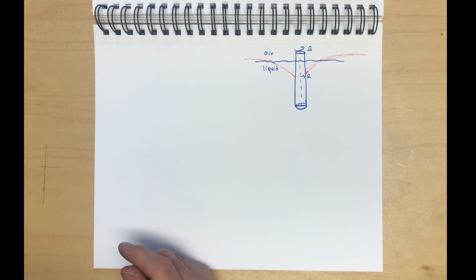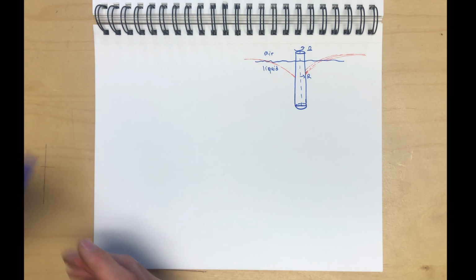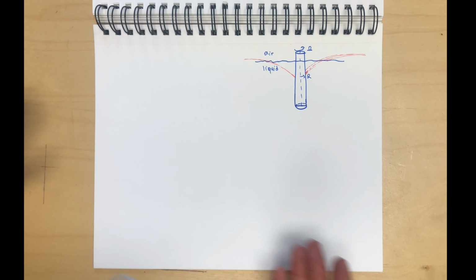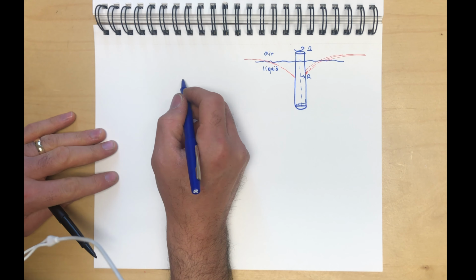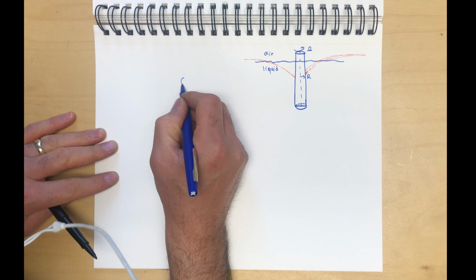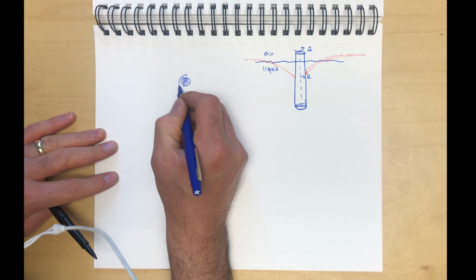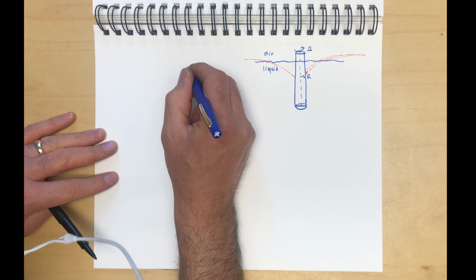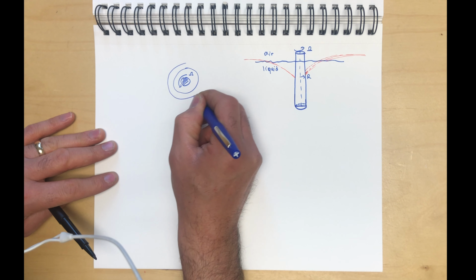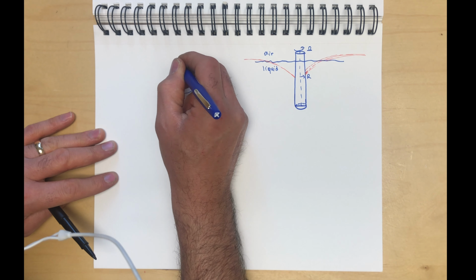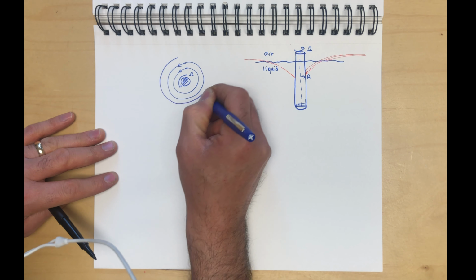Well, the first step is we're going to assume that this is a steady state flow, constant properties, etc. And we've already visualized the flow. Now from a top view, you're going to see the rod in the middle over here spinning at a constant speed omega. Then you're going to see the streamlines centered at the rod, and they change with the distance from the rod.